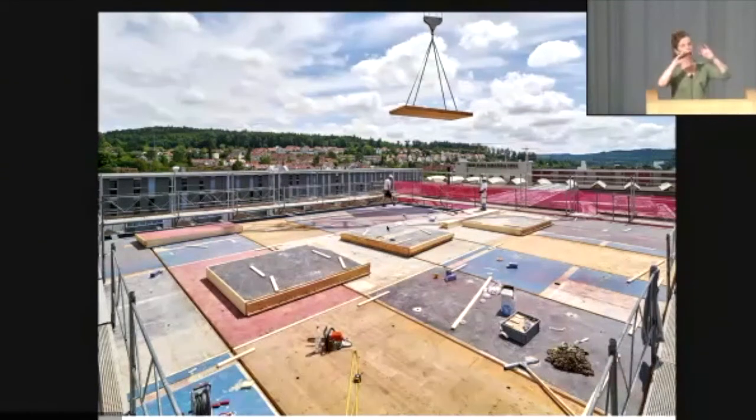We said, okay, we look at the whole building as a system: it's about this amount of window surface and that quality of window, which means we need that quality for the wall. So this was a rolling process, going back and forth. If I find windows that are not good enough, maybe I just need a bit less window surface. As long as it's within a reasonable range, you actually have quite a tolerance, a playing field in which we as planners can play. Here we didn't fulfill the code for this roof, so we added another layer of insulation on top. Then it worked.